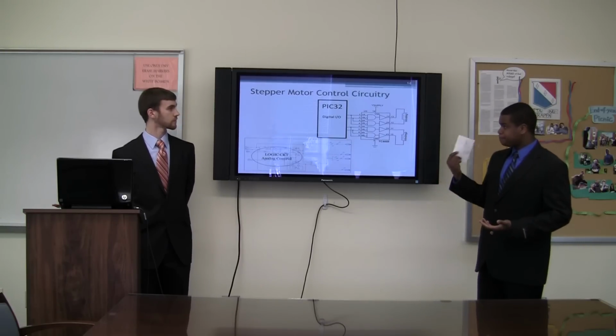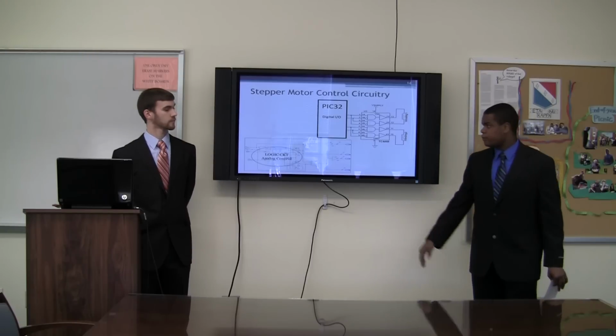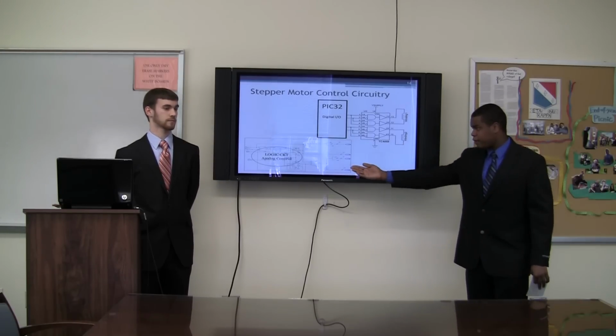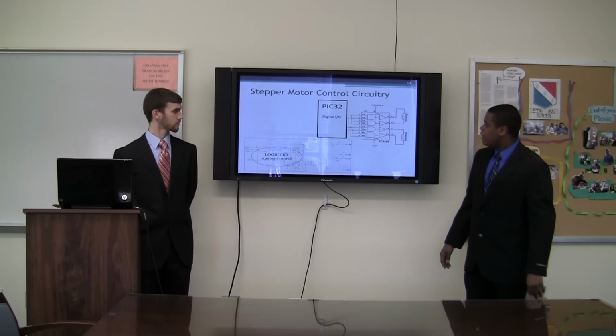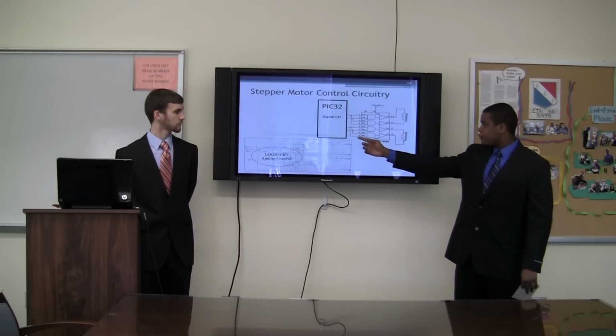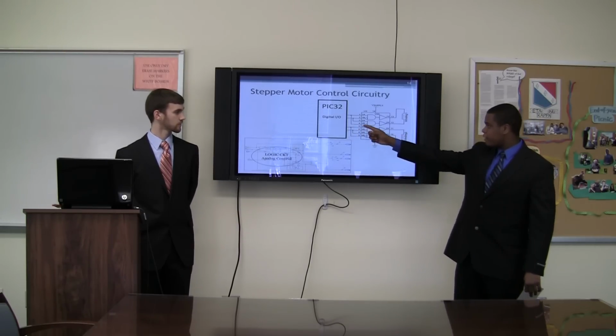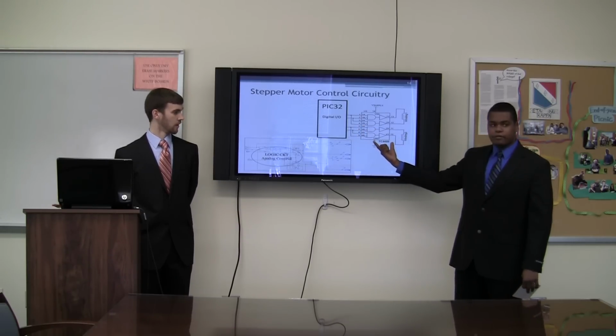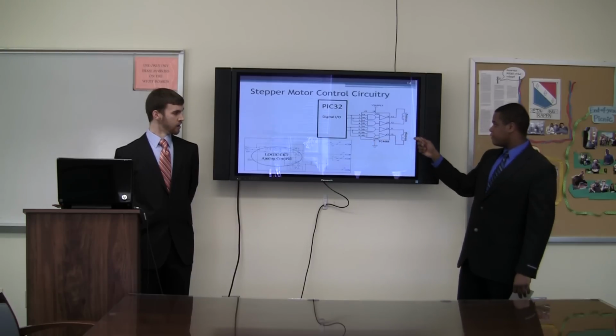And there are 2 different methods you can do this. You can do this by digital I/O, or you can use the analog logic circuit. We use both of these in our project. We use the PIC32 for the I/O pins from there. We can use this as a CMOS quad driver, and we connect it to the windings of the stepper motor.